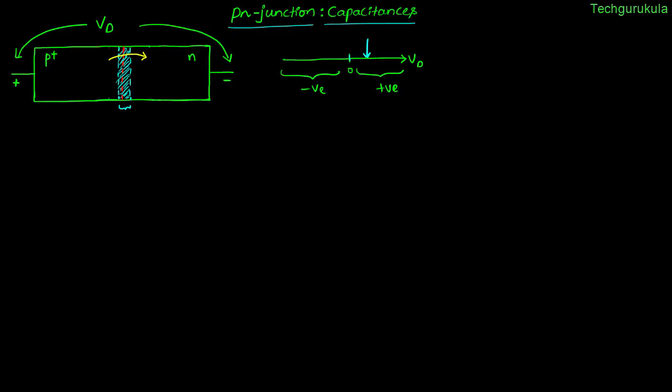And similarly, the electrons would be injected into the P side, and the same scenario happens: electrons would see a concentration gradient and they try to diffuse, recombine with the majority carriers holes, and the injected electron concentration would be decreasing as they go deep into the P side. For a given voltage, the process of injection and recombination would be constantly happening. As a result, the concentration of excess electrons in the P side wouldn't change with respect to time.